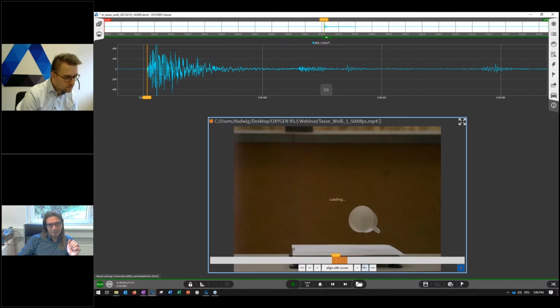And when the scan is hitting the surface here, this is my absolute instant of time of synchronization where the acceleration was measured, which is, oh, no, that's too much. I go back a little bit in time and then align it frame by frame. And this is the instant of time where my video data absolutely corresponds to the sensor data. So I have now determined the offset between the sensor data timeline and the video data timeline manually.